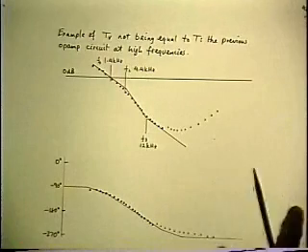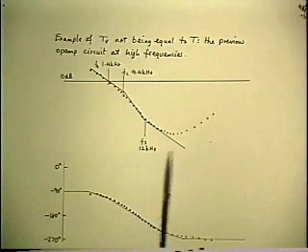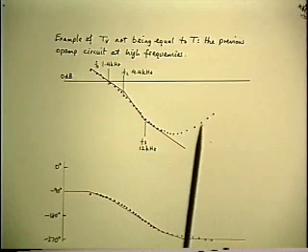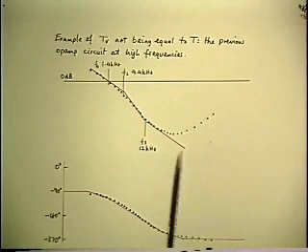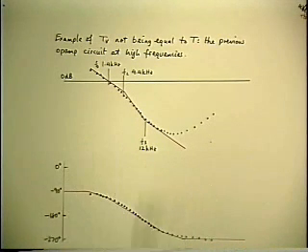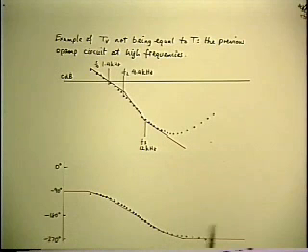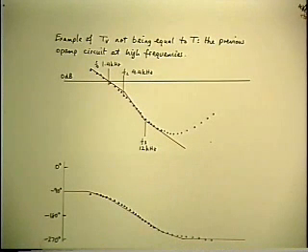So the conclusion from this little exercise is, if you predict a loop gain from a system you're designing, and you then make measurements and you get a discrepancy between the measurement and the prediction, one of the reasons might be your prediction was wrong and you better go back and check your model and your analysis. But another possibility is the measurement was wrong. Not wrong in the sense that the measurement itself wasn't correct, but wrong in the sense that you weren't measuring what you thought you were measuring. That's more subtle and therefore more dangerous.